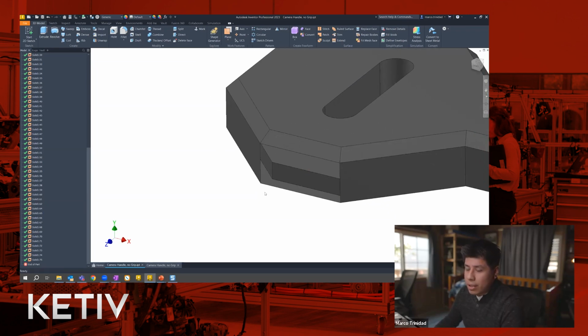So in order to patch it up, I'm going to go up to the patch tool, just right up here on our surface tools. Now, if I just hover over these, you can see it's selecting a loop. I don't want it to select a loop right now, so I'm going to turn off the automatic edge chain.